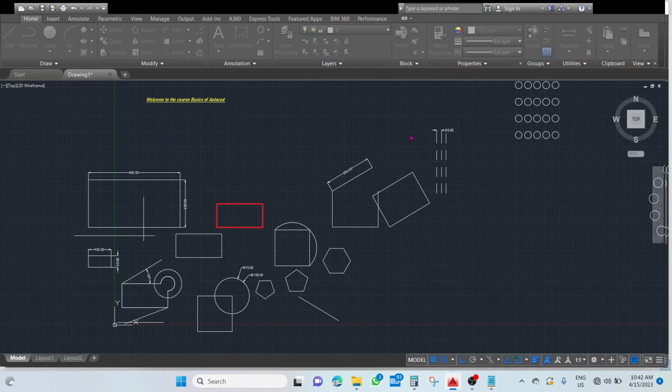So click on load. Here basically I want the center line. So click on here, just press C. All the lines with notation alphabet C appeared over here. So I want the center line. Then I require the hidden line also. So click over here, press H. So filter of H. Okay, I want the hidden line. So these two lines I require for drawing.